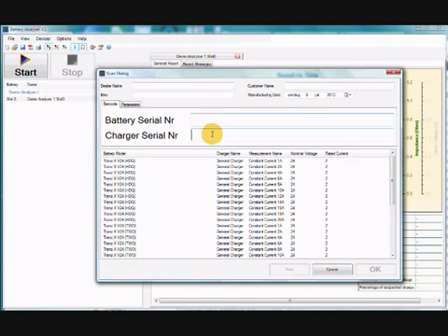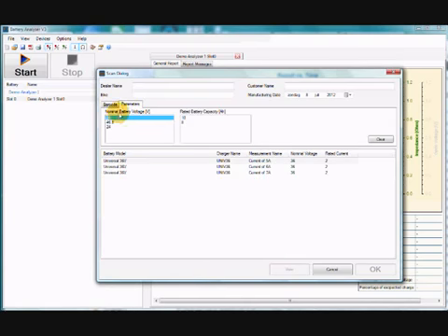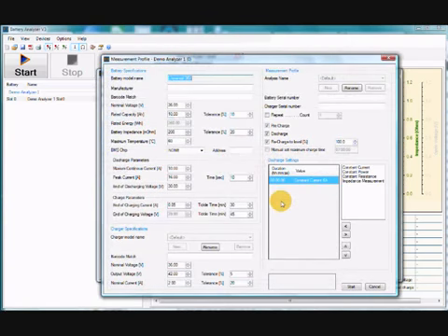If the entered barcode does not match any profile, one of the universal profiles may be selected based on the parameters. Now I will demonstrate the use of a 36-volt battery of 10 Ah, and I will use the constant current test on the 6 ampere. Pressing View will show the battery profile dialog, and you can make changes to suit your needs for this battery. Pressing Start will start the test immediately.